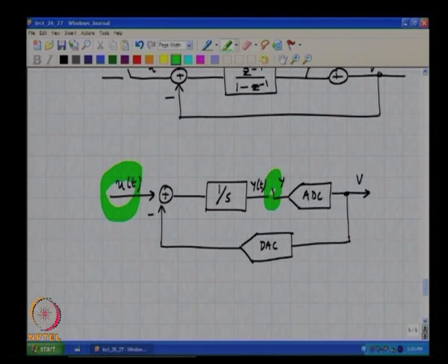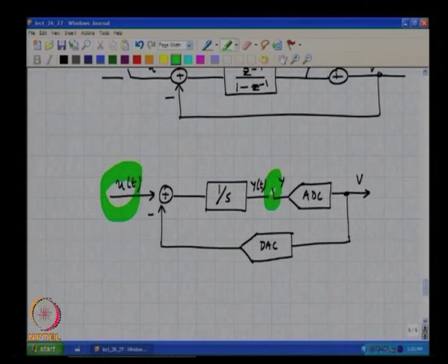If the same thing happens here, then we will say, hey, that is too bad, it is nice that we are able to realize the loop filter using continuous time circuitry, but we still need an anti-alias filter upfront to kill any signal components at multiples of the sampling rate. So, we will see how this loop behaves when a tone at multiples of the sampling rate is put. Okay, we will do that in the next class.